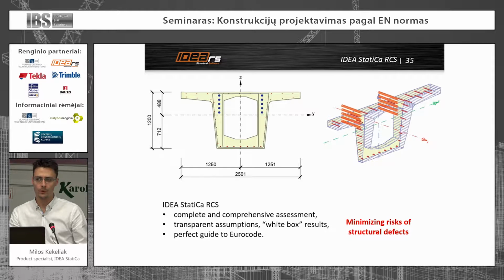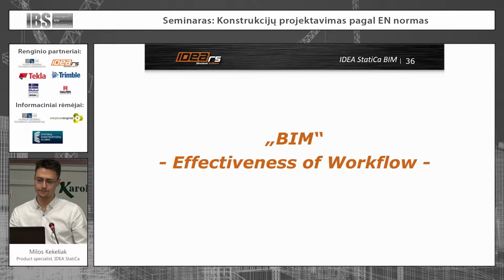So all the reports provided by Idea StatiCa for concrete or pre-stressing are presented in a form where a structural engineer can really simply identify the clause from Eurocode based on which the check is done. Every check that is done in Idea StatiCa is presented with a reference to the code, the Eurocode clause.